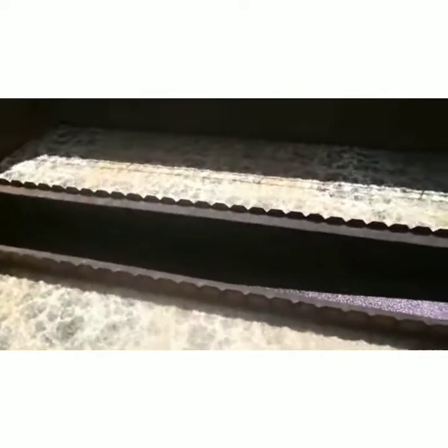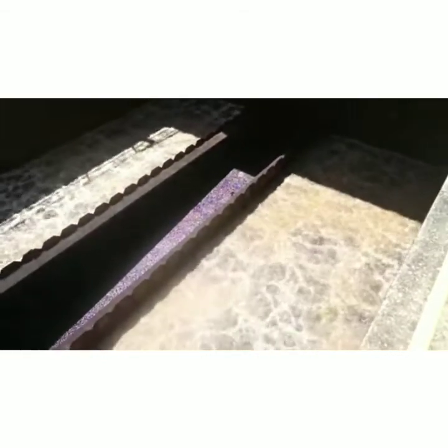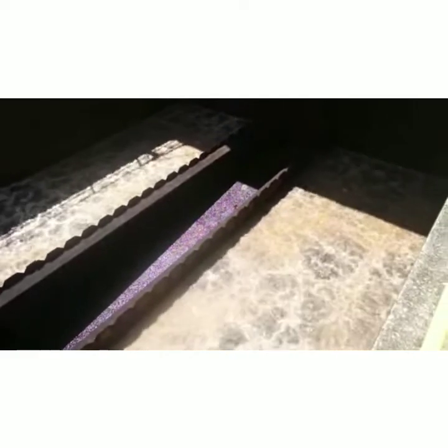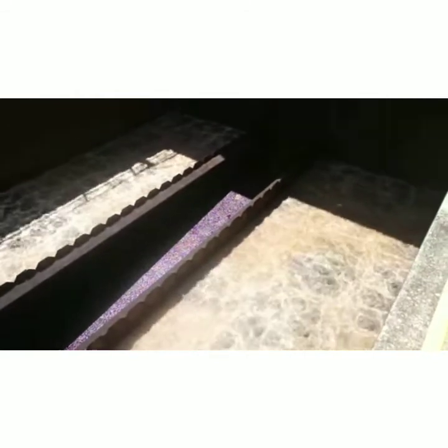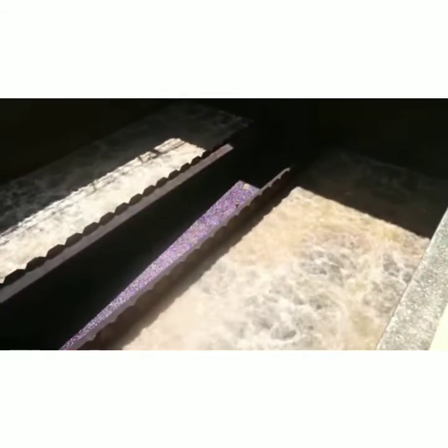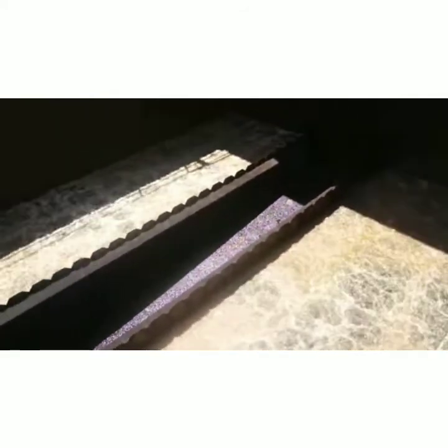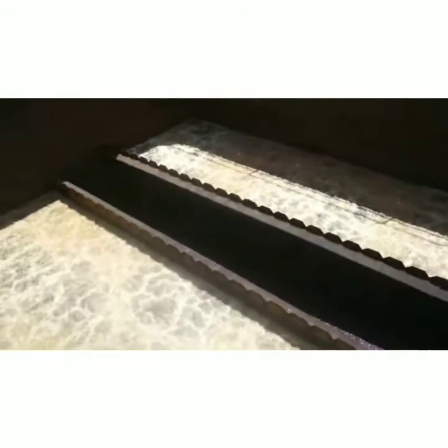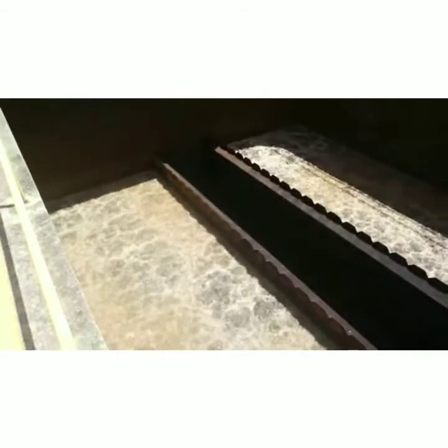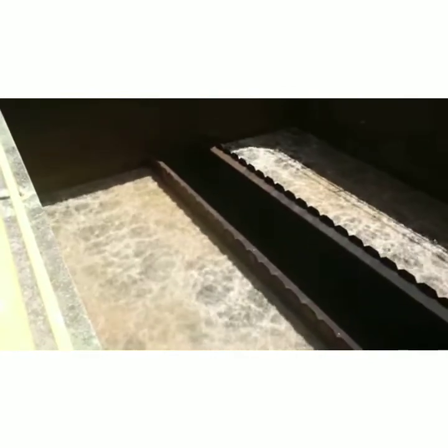Water is already present, and they have given the air pressure, so the air tries to escape from the pores, but during the filtration process the pores are completely filled by impurities. So when you apply the pressure from the bottom, the air starts coming out from the top. During its path it brings the impurities which are present throughout the filter media. You can feel it is like boiling.